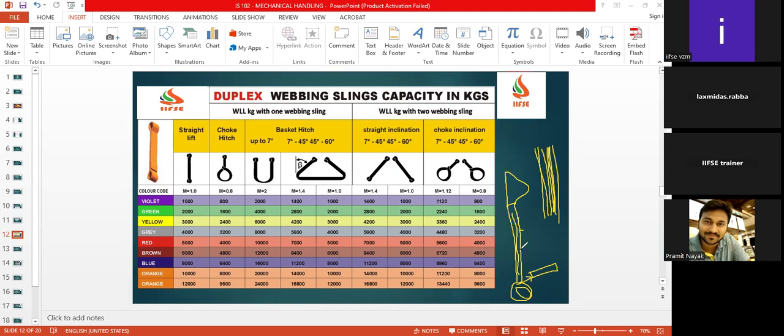We have to display them in the work areas, so that if somebody sees any one of the criteria being met, then immediately we can discard the belt, because otherwise a tear can make a bigger damage even if you are lifting just 1 ton of load.